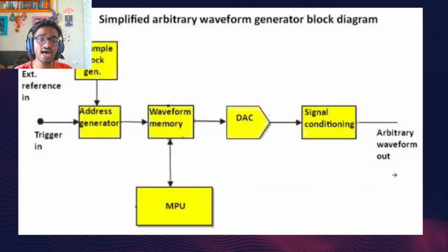Moving on to the arbitrary function generator's block diagram. It has always been a significant design challenge to create stimulus signals that can fully exercise a prototype. In the case of RF applications, complex, high-frequency modulated signals with jitter, spread spectrum clocking, and other time-variant effects have traditionally required a benchtop of pulse, function, modulation, and RF generators.